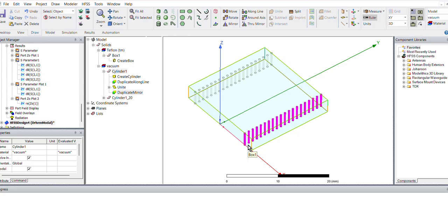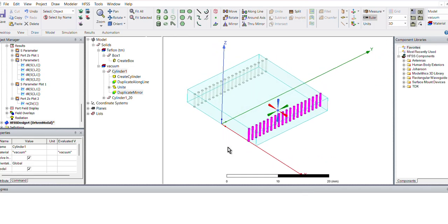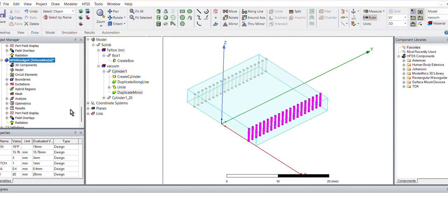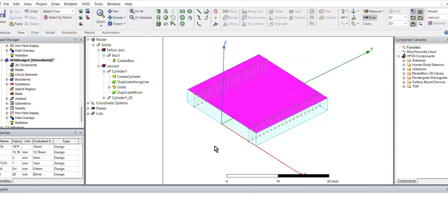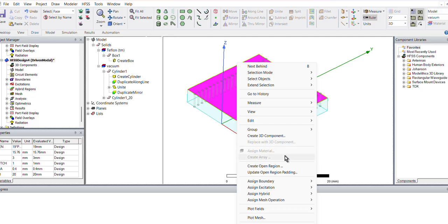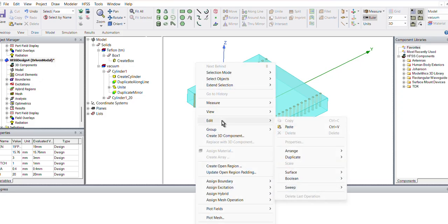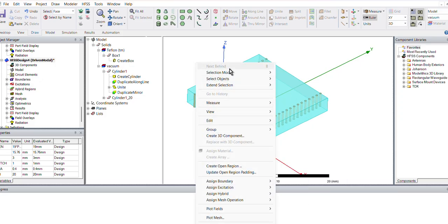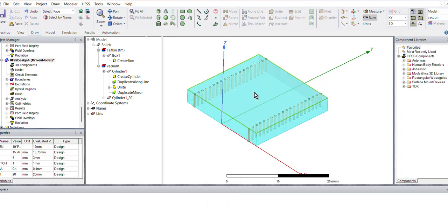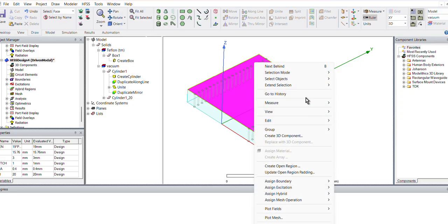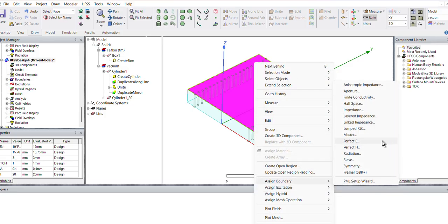But sir, it says you have not put any metal on top side and bottom side, and I will say because this structure, HFSS itself provides PEC, I have not given. But in this particular case, for ease of understanding, I am going to assign that. So I shall make the top plate. So what I have done, I am going to go to edit. I am going to go to selection mode, faces, top face. I have selected. I can directly assign it as a conductor boundary.